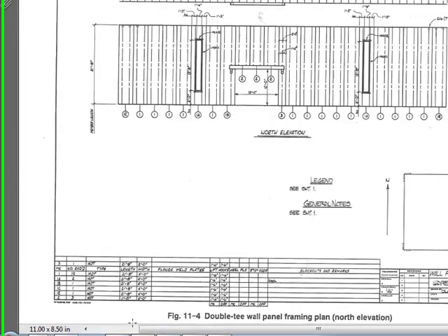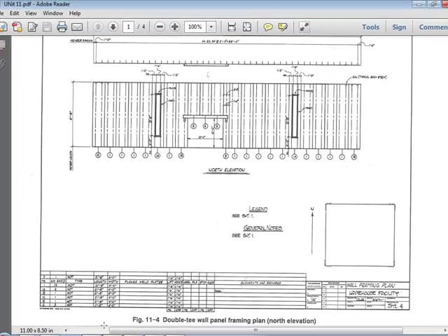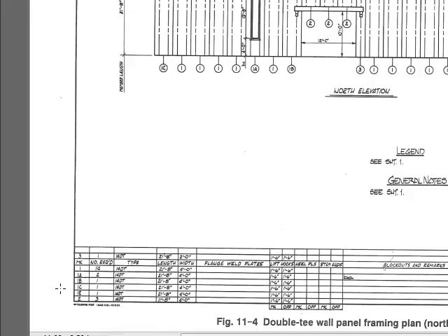And you'll need to note that in your schedule, and then anytime that length changes, you get a new kind of beam or a new mark. So the easiest way, and this is describing the old-fashioned way of when we had to hand draw, but it's kind of the same with AutoCAD. After you get number 1 and 2 done, you would overlay on top of your column framing plan and trace the columns. Of course, you can just copy it over to your beam framing plan and make them hidden lines.